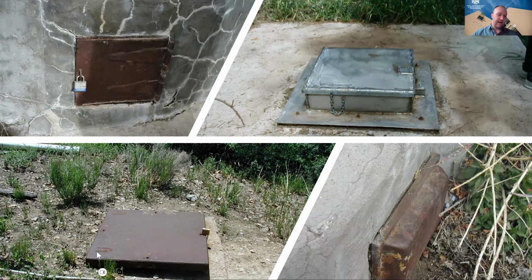Because you can see that this box, this shoebox lid, is right at about the ground level where there's some runoff that is probably going into this spring box. So in that case, it may be treated as surface water. And these are just the sides of this box with some vents or access hatches. These don't look completely sealed from the outside, so these may not be totally adequate for sealing that box in and having it still considered groundwater.